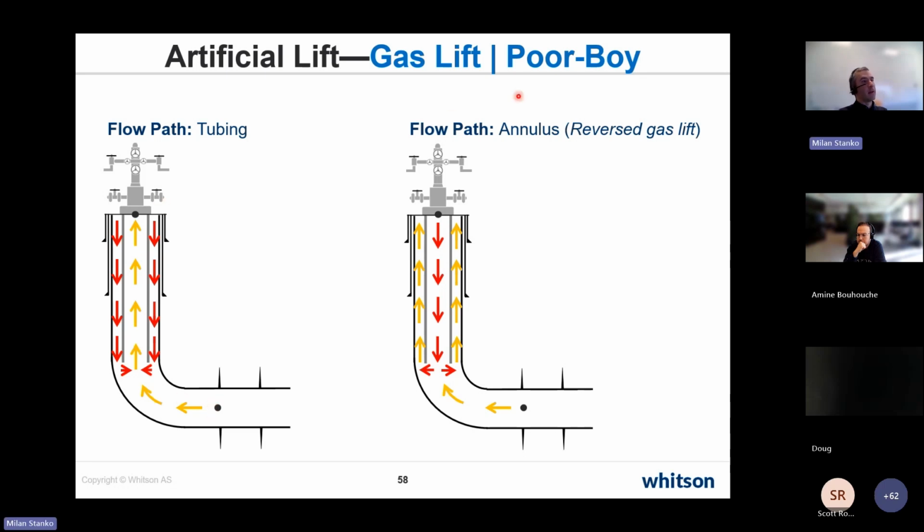And if you use the reverse gas lift, in which you are injecting through the tubing and producing through the annulus, it's the same. Essentially, you're calculating from casing head pressure, assuming formation fluids and gas lift gas, all the way to the end of tubing, and then from end of tubing you calculate the top formation pressure using just the formation fluids.